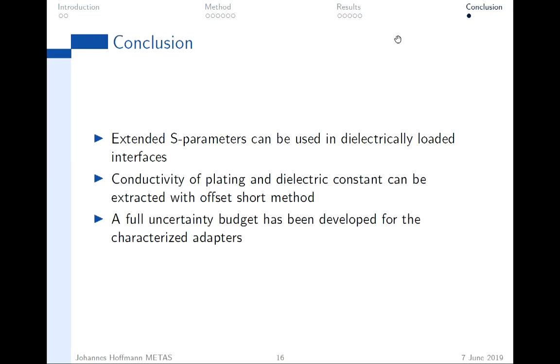So you need to come up with a definition which allows for multi-mode or arbitrary field in the reference plane. And we are just using power and current to extract S parameters. From power and current we go to the transmission line equivalent model, and then we get the S parameters. That's our technique. The consequence of doing so is that you have to check what's happening if you change something very close to the reference plane, because then you change the field you're referring to, and this also has consequences for the adjacent S parameter block. And that's why I made this test when I changed L7. So, welcome.